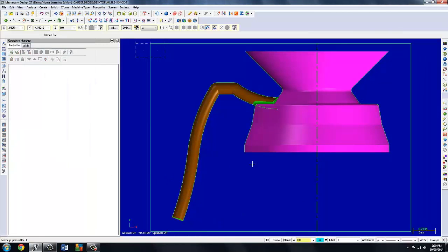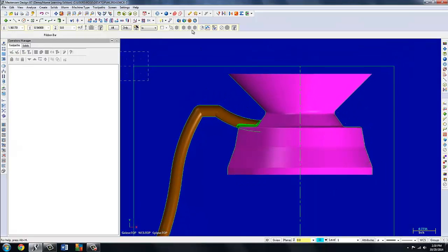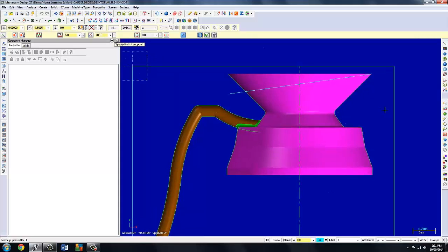Before we can put the draft surfaces in, I need a couple of lines, so I'm going to go to line endpoint, snap to this intersection, and come off of this part a ways. I'm going to pick a distance of just 5 inches, so that's plenty. My angle is 8 degrees on my drawing, so it's 180 plus 8 for 188. Hit enter, and we've got our line. If I just wheel this, it'll repaint. I'm going to apply that, and I'm going to put another line in. Just call this one horizontal, and I'll put it from here to here, and then I'll place it on its coordinate after I'm finished.